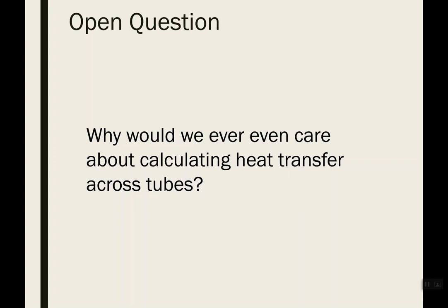A heat exchanger, yeah, so we'll get to heat exchangers. A heat exchanger, that's chapter 11, that comes after convection. A heat exchanger is a device that's designed to transfer the maximum amount of heat. According to Newton's law of cooling and every other heat transfer law, the total rate of heat transfer is proportional to the surface area over which heat transfer occurs. So for convection, we would want to increase the surface area. This becomes super important if you become a design engineer or even a process engineer where you'd want to characterize the performance of your heat exchanger.